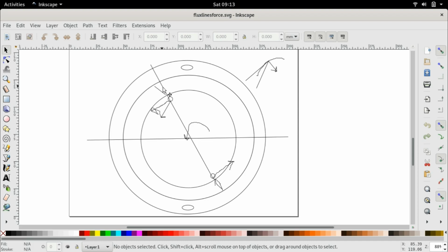And the reason was pretty simple. We said that even though a vast amount of the magnetic field will be well behaved and fairly uniform, and will choose the path of least reluctance, which is along the radius of the cylinder since this is a cross section, this magnetic flux along the radius will result in a mechanical force that is tangential to the rotor, and therefore it produces a purely rotational torque.